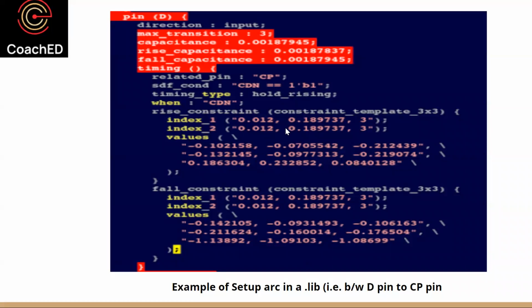That's a good question. Usually, depending on the tool or which company it is, they have some methodology at their end where they may say, okay, this is the operating voltage where I'm running the simulation, and these are my usual clock periods or clock cycle times. So I can possibly use some percentage of clock cycle time as input transition values, go from a very small value to a very large value, and set them.